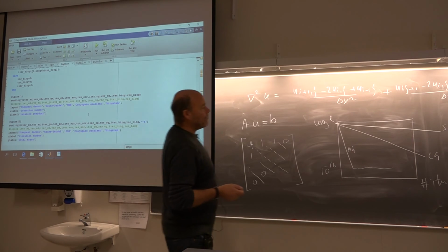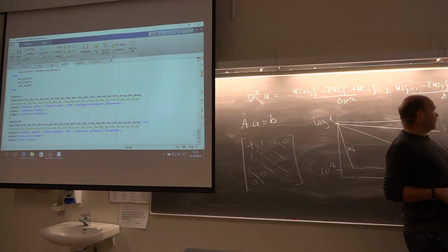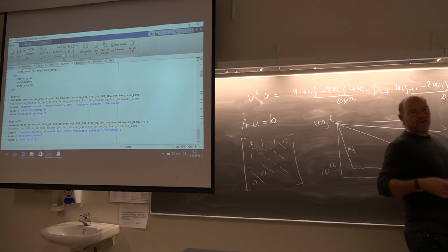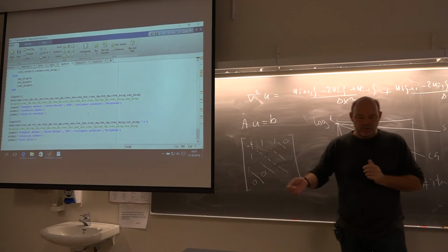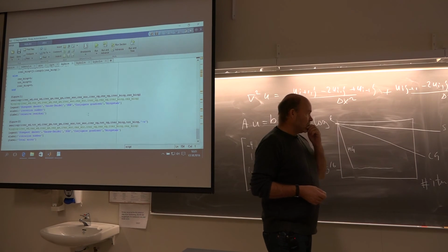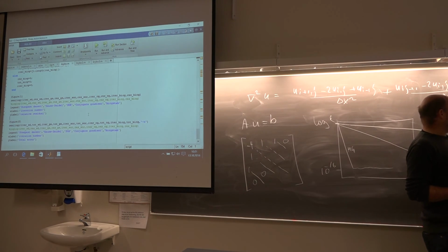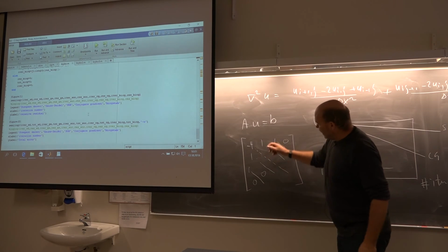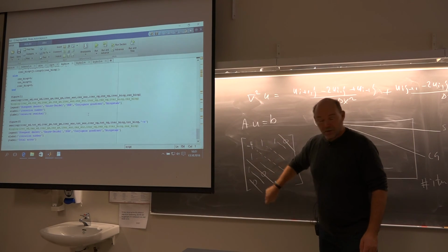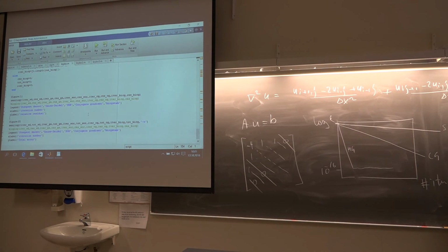You see, if M equals A, then you have A inverse multiplied with A, that's just 1. So then you have the solution directly. M is sort of trying to help transform the equation system to a system that is closer to the solution. But you pay the price. A good preconditioner would be efficient, but you will blow the memory. The more efficient it is, the more additional extra bonds you get in your coefficient matrix, the more memory you're going to need.